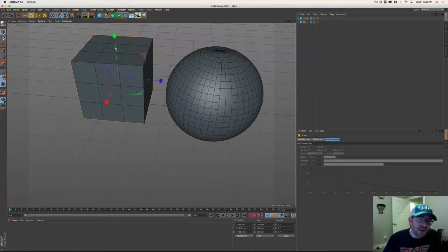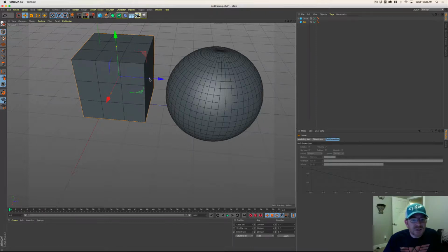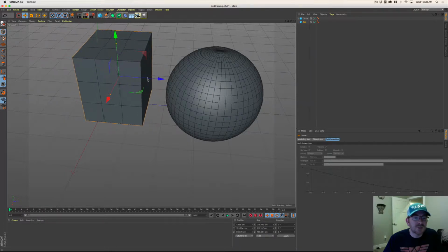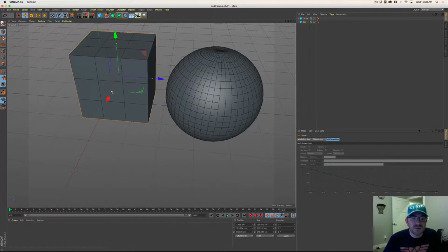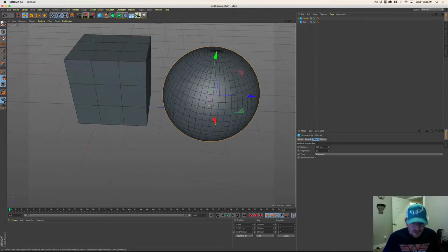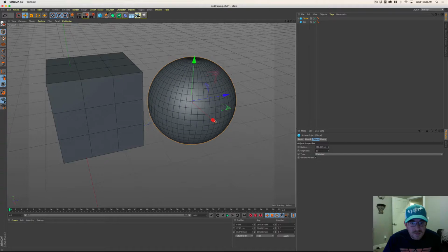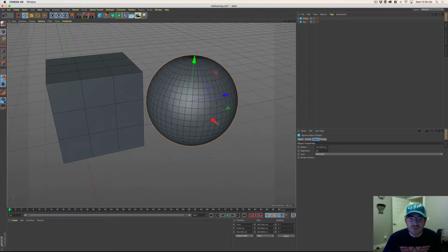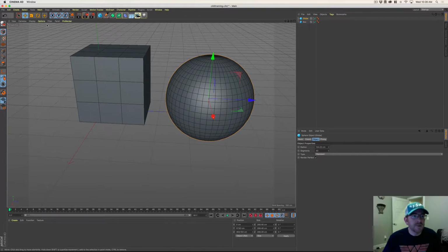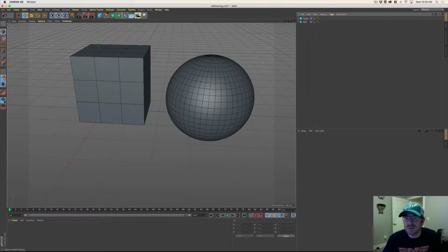There's another little tiny widget here. There are little buttons there. So let's say I have my move tool. I can also scale it from here in its individual directions, X, Y, and Z. So that's another way to scale objects if you see some of these little buttons here. In my sphere, I have one little button, and that controls the radius. So some of these objects have those abilities. Those are easy ways to navigate.